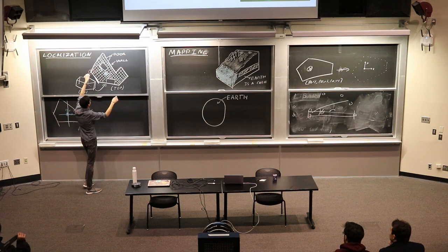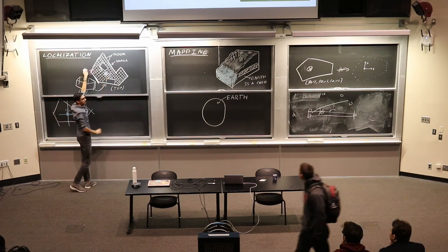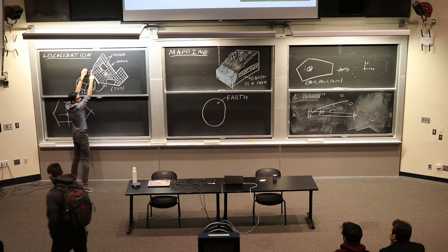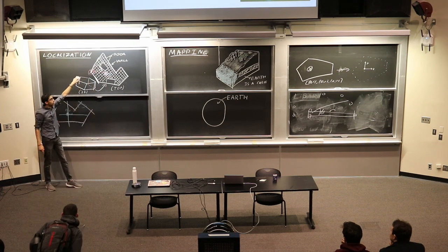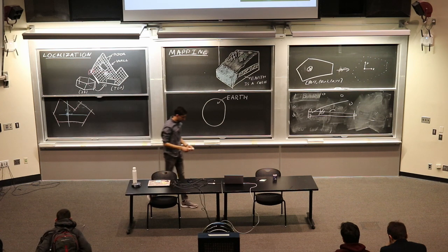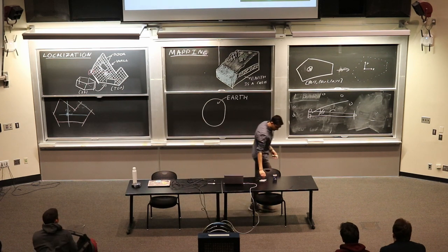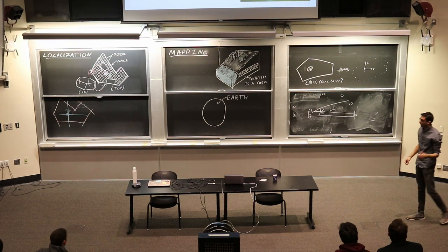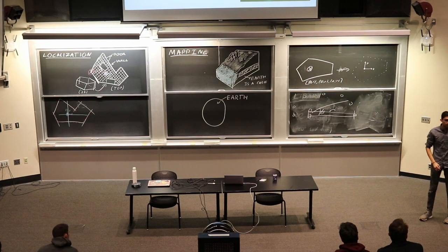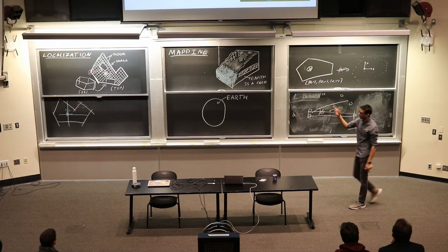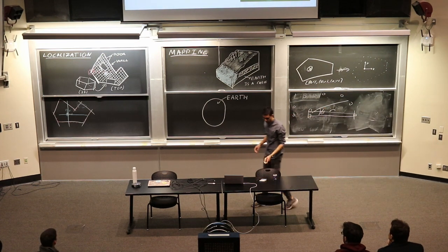I've matched the scans. This is the origin of the scan, which means with reference to this 0, 0 origin of the map, this is where my robot is. And that's localization. So localization in one sentence is, I know what my environment looks like, but I don't know where I am. This is one of the ways you figure out where you are.